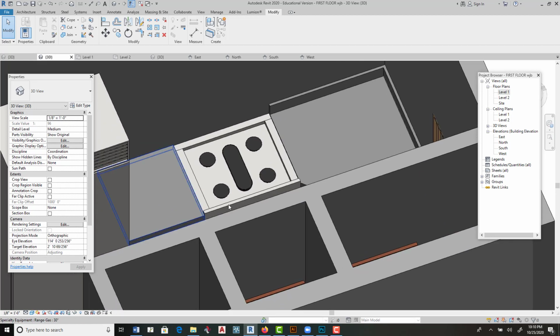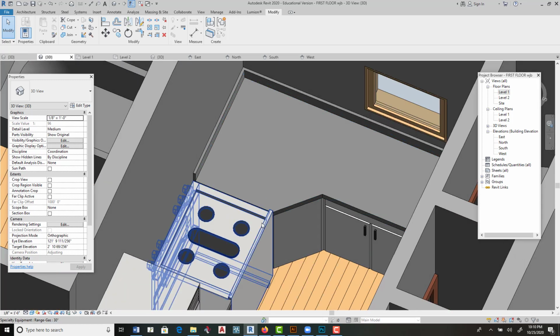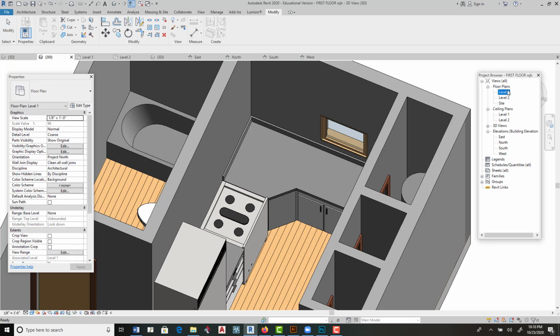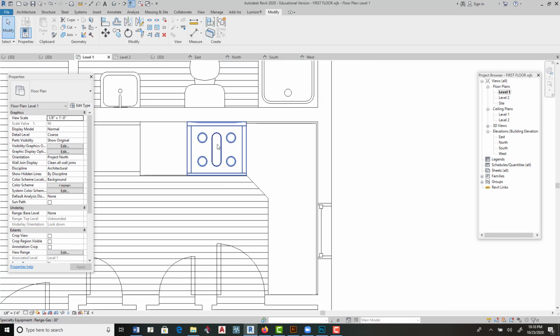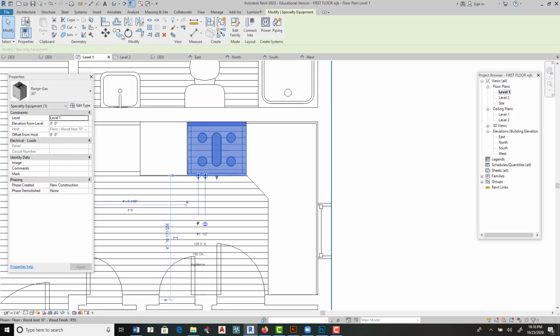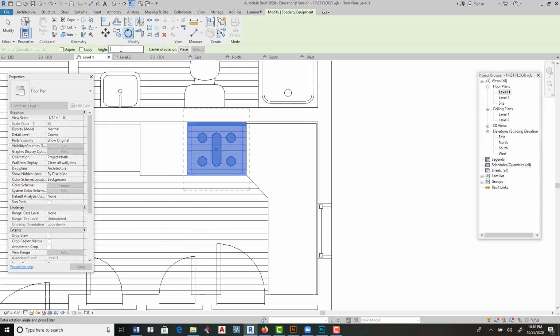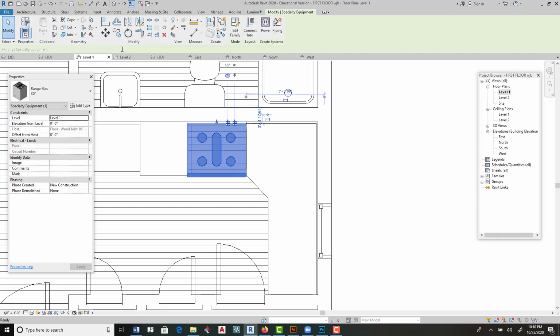at the counter. And look, I made a boo-boo. I put my stove in backwards. So I'm gonna change that. Looking at the backsplash, let me know that. So I'm gonna click on there, and I'm gonna go to rotate. The angle is 180. Enter. Bingo, there it is.